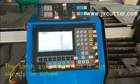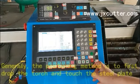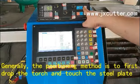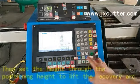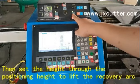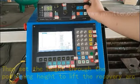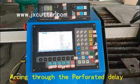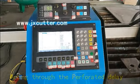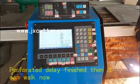Generally, the positioning method is to first drop the torch and touch the steel plate. Then set the height through the positioning height to lift it and restore the arc. Arcing through the perforation delay. The perforation delay finishes, then it can move.